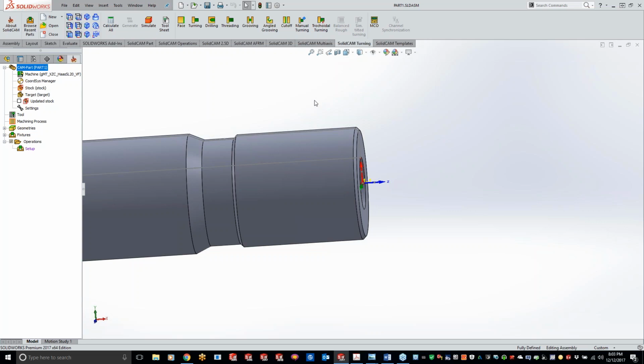So when you guys are doing your parts in SolidWorks, you don't have to draw up your threads at all. That's more or less just a waste of graphics and time for creating them. All you really need is the major diameter drawn up. So for this particular part right here, we are running a 3 3/4 by 4 thread. So fairly large threads right here. Now you can do custom threads, or standard threads, or pipe tap threads. The sky's the limit on what you can do for threading.